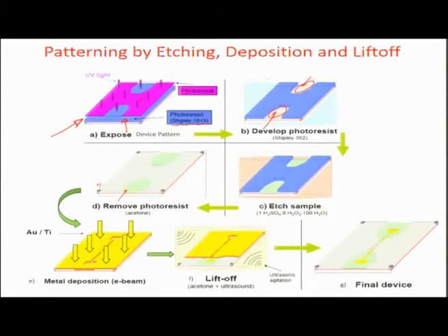And then after doing this, the photoresist is removed and another layer is coated where you can actually carry out metal deposition. So, this is again lithographed, a pattern like an interconnect is created, vaporization of metal is made on the top surface, and once the metal comes and sits on the surface, the green area, you can take off the resist layer so that you have interconnects on the final device as is mentioned here. So, patterning by etching, deposition and lift off all at one go is in fact represented in this particular slide, which gives you an idea of what can be done with interconnects, with etching features and structures, producing mechanical and electrical features, and a variety of things as per plan on surfaces of materials like silicon.